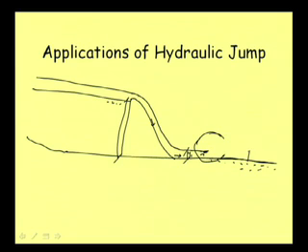Well, so for that many a time some obstruction is constructed, called a stilling basin, and this part is made concrete. So, when this part is concrete, even if water is moving with high speed, this will not cause damage. The water level is raised to a certain depth by this sort of obstruction, which of course we need to design properly. We raise the depth to such an extent that it becomes subcritical flow here. This is supercritical, this is supercritical.